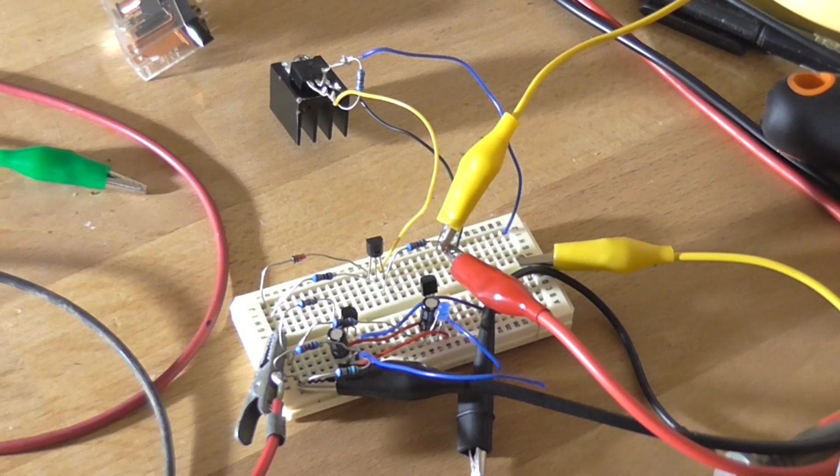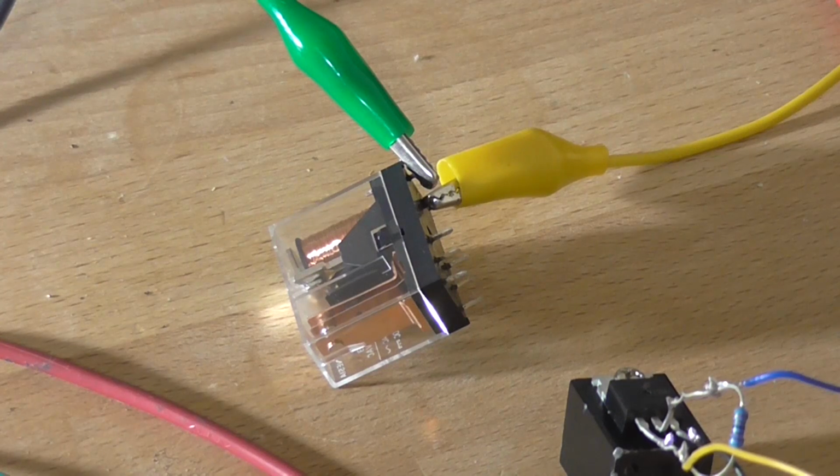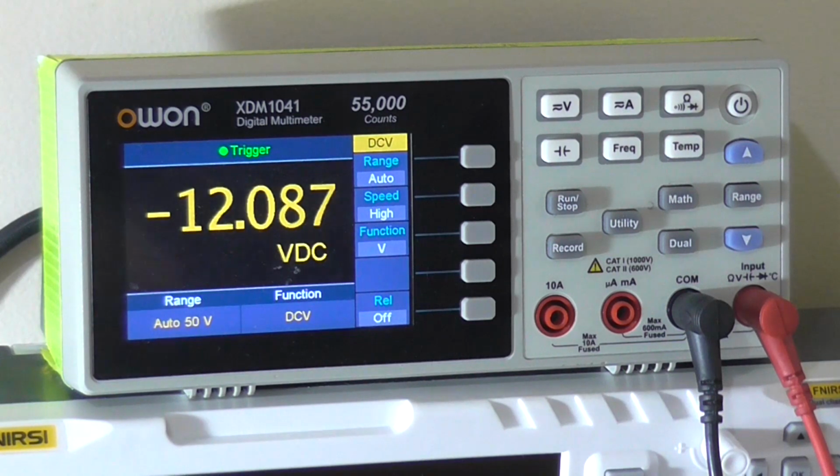But how about if we load it? Well, as you can see, I've got a relay sitting up there in the background. That draws around about 44 mA. So we'll hook that up across the output and see if we get any voltage drop. So I'll just connect this to the negative. We get a slight voltage drop, but not much. So I'll disconnect it. We're probably losing, I don't know, I want to say 40 odd millivolt, maybe less. Yeah, about 40 millivolt we're losing, which is not bad.